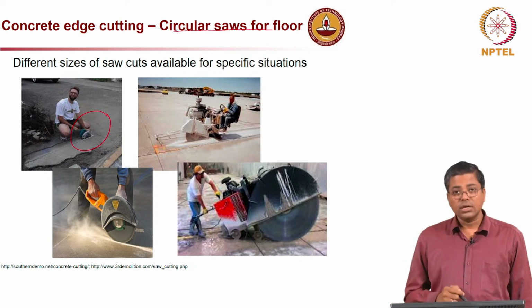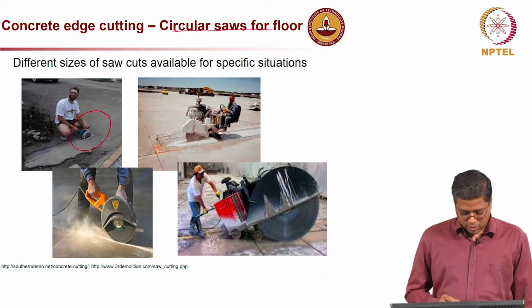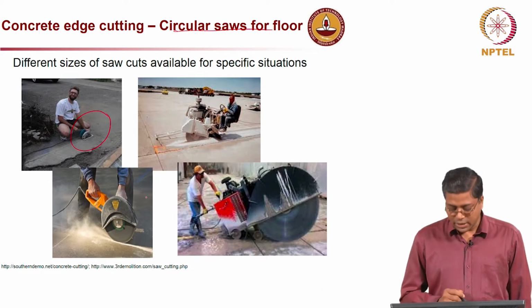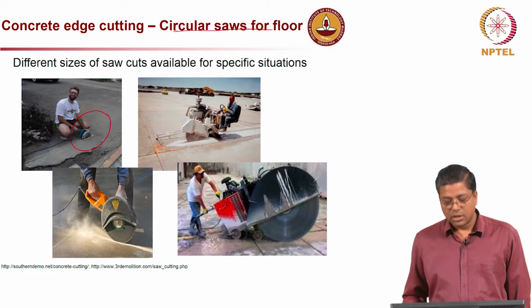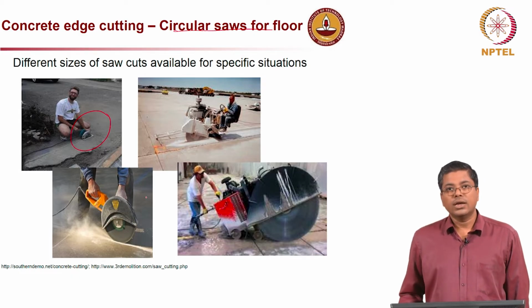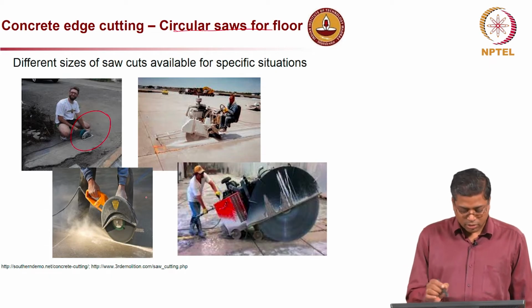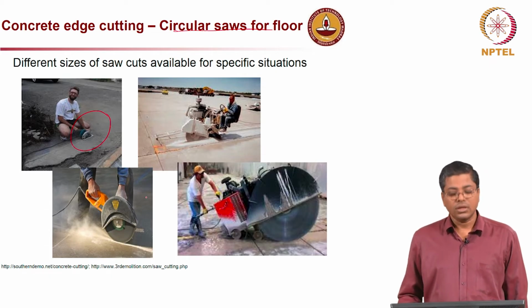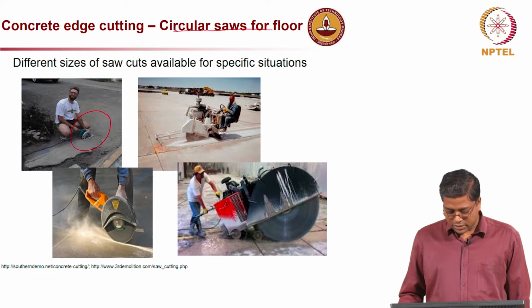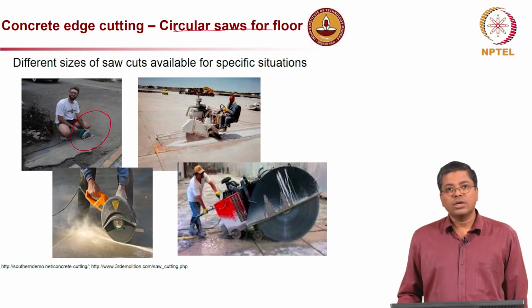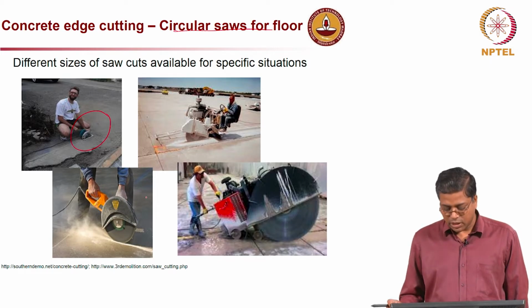You can actually go for different types or sizes of blades, and that will really ease your work, and then at the end you have a very nice edge cutting, or a well defined edge for the repair region, and at the same time the work is done in a very short period of time.